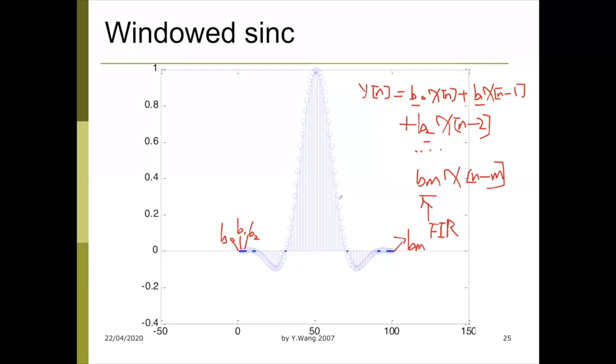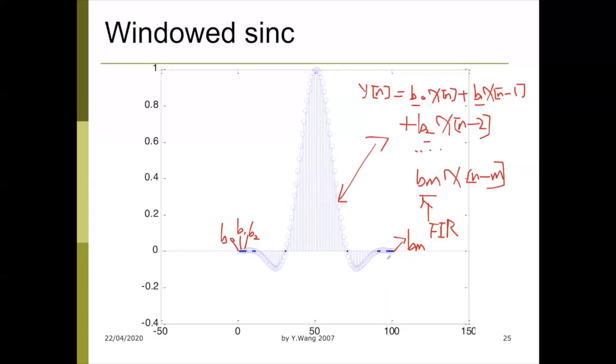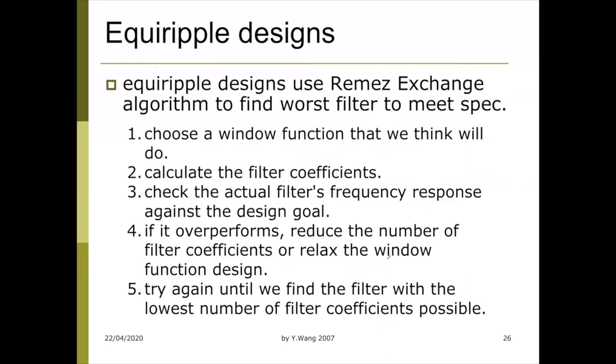So the digital filter can be represented in both a mathematical formula as well as a graphic way. Is that okay? The problem when we're doing digital filters is that in FIR filters, sometimes the filter kernel is quite large. Look at this, it's 100 coefficients. It's not very convenient to write that in the equation because we have to write all the 100 coefficients. So we just take the coefficients and plot them in a graphic way and save that as a filter kernel. I hope that's clear, but certainly we can discuss in the future if you're still not very clear about that.